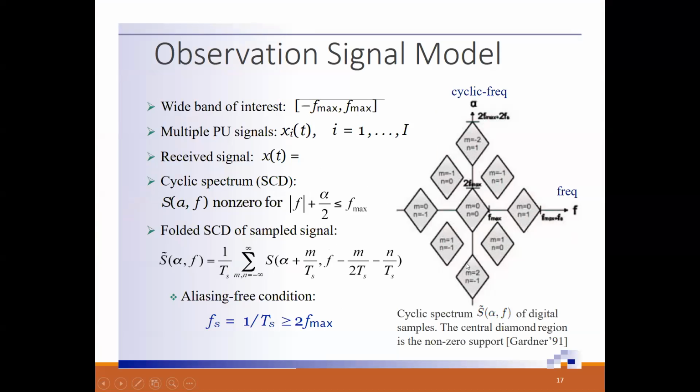So different signals have different occupancy levels. For instance, if we have this 1, 2, 3, 4 like this one, that corresponds to a BPSK signal. Another, QPSK, will induce a pattern like 2, 1, 3, 4. So out of the tiled diamond structure across the two-dimensional plane, by controlling M and N, you will be able to identify what kind of modulation that signal has.